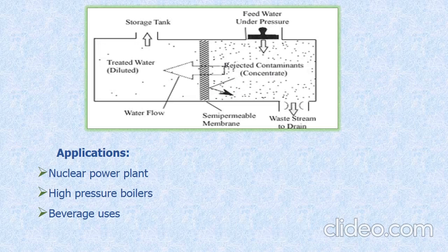So this is the diagram which you have to draw in the university examinations to explain the reverse osmosis. See here, the middle part we have the semi-permeable membrane. So this side we have the impurity and here we apply the pressure. From the pressure we have the treated water. So this diagram we have to draw for your university examination so that you can explain reverse osmosis. So this is a block diagram of the process of reverse osmosis.